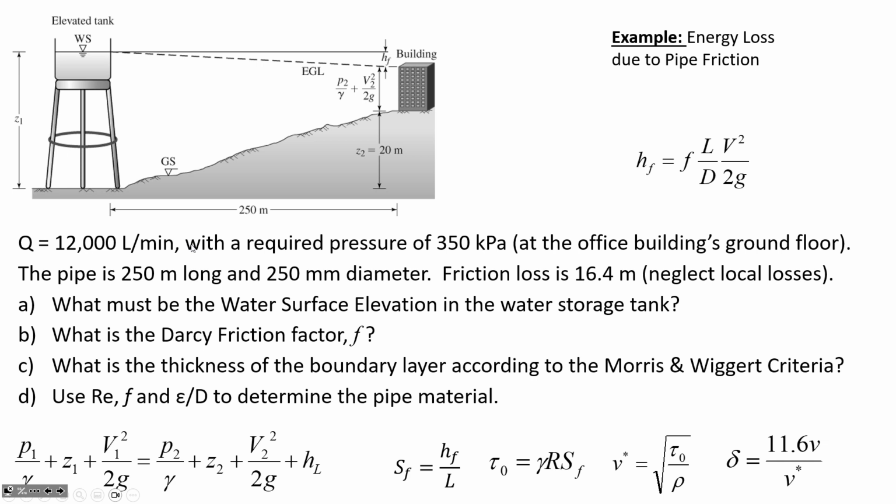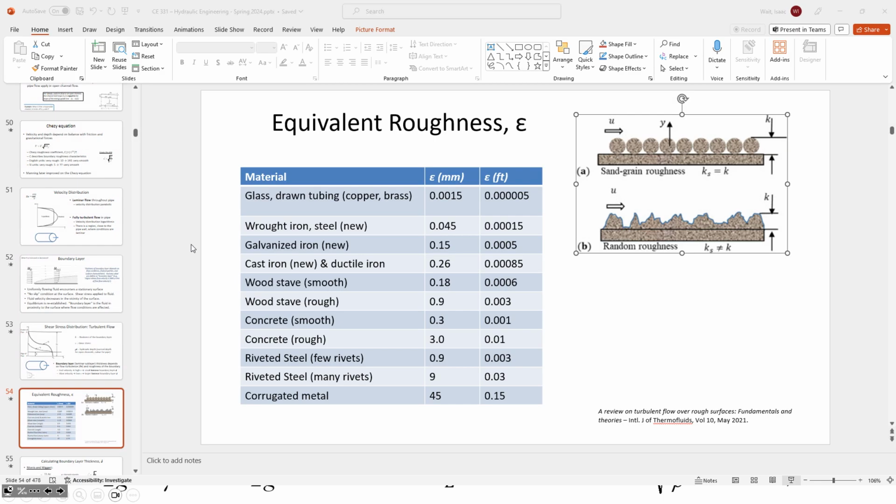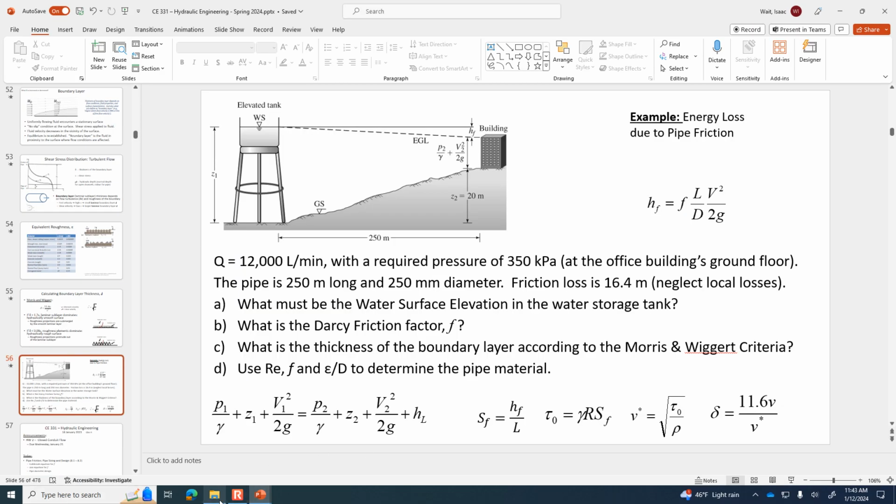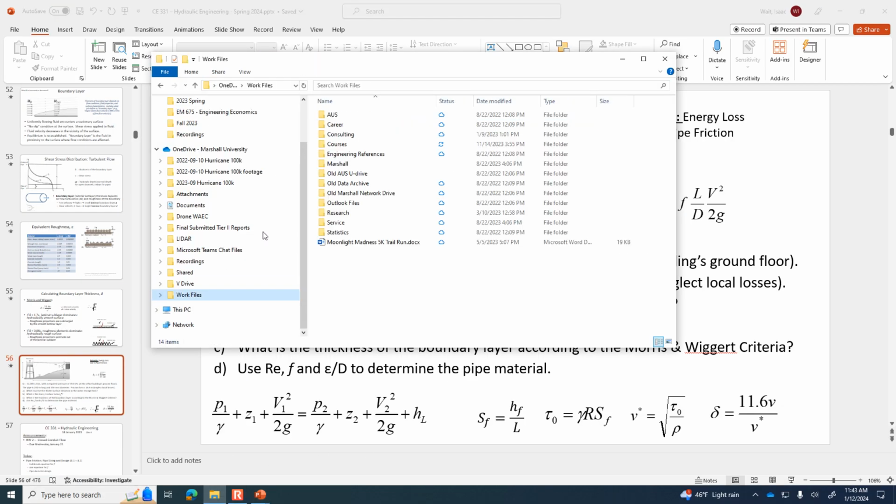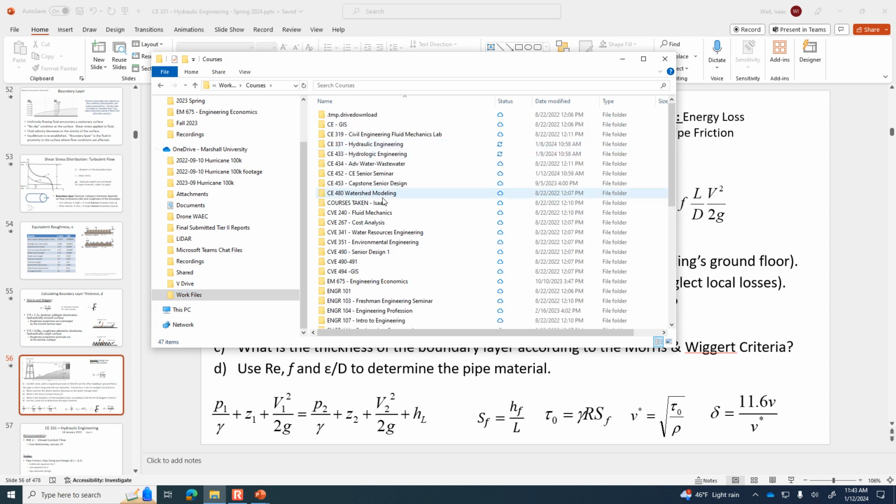All right, so now, I was going to suggest earlier that we neglect the velocity head at 2, but I'm glad we didn't, because 4 meters per second is a pretty significant speed, and so the velocity head may not be negligible after all. I'm going to erase this part where we determined the velocity. Hopefully you've got that copied into your notes, and maybe I ought to bring it up on screen just so that it's included on the video for the benefit of anybody who will be reviewing this later.